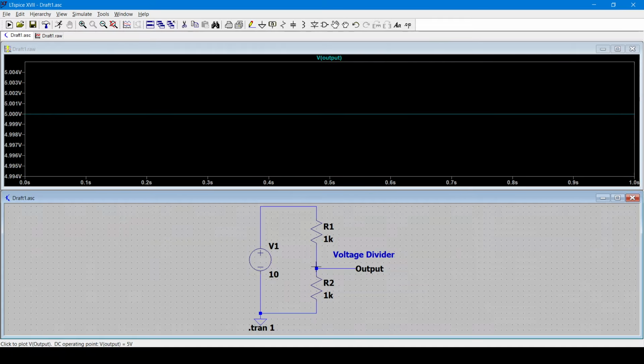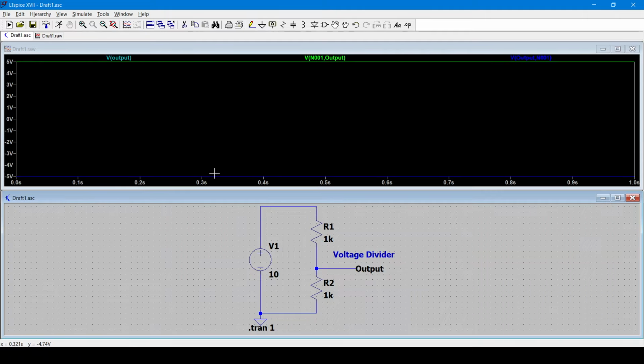Now all the voltages that I have been seeing until now are referenced with this ground. So if I need to see the voltage between 2 points, for example this resistor R1, what I can do is I click here and I hold on my click and I drag it around the resistor. So when I stop clicking or unclick, I can see the voltage across resistor R1. If I do it the other way around, meaning I start from here and I go around it, I can see the voltage is -5.